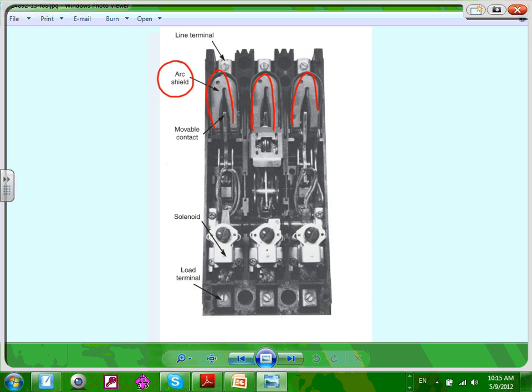Your goal, William, is two. Number one, move the arc away from the contacts so you don't burn them, the contacts that open. So when you open, you want the arc to move away from the contacts. Number two, you want to extinguish this arc as fast as you can and vent all this thermal effect, the gases and all the stuff, outside. So move the arc away and stretch the arc so you can extinguish it and move the exhaust outside. All these are different technologies the manufacturers of circuit breakers use to achieve the same thing. Move the arc away from the contacts, stretch it so you have enough time to open it and extinguish it, and exhaust all this mess that happened inside your vacuum outside.